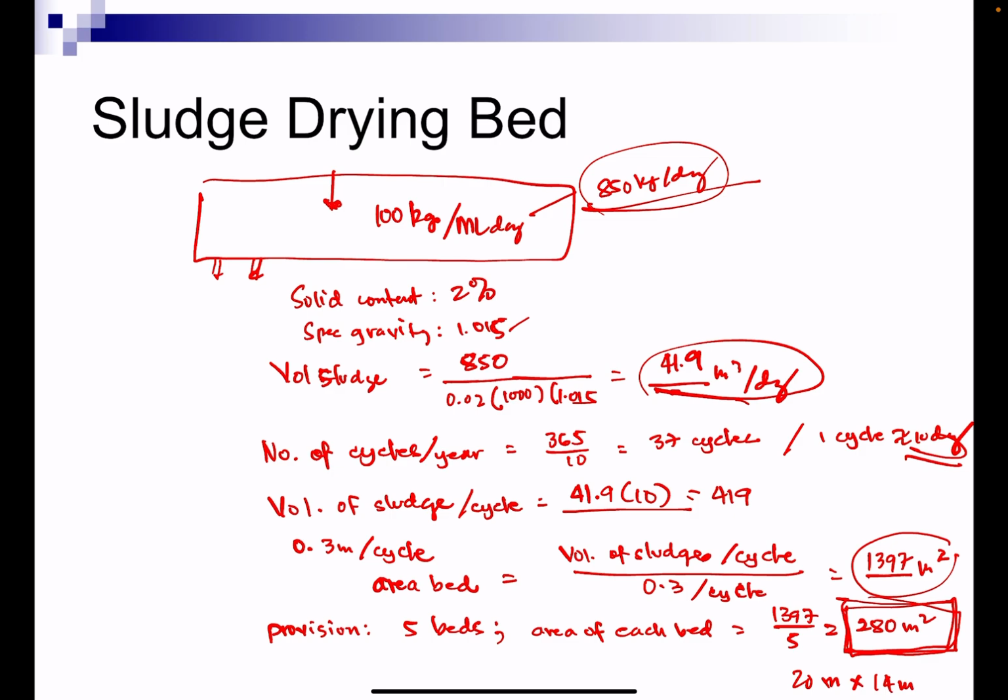Note that all computations will definitely adjust when the actual volume of water supplied is available. For example, if our assumption is on a per capita basis, say 235 liters per capita per day, that is where your computation will start, which is your assumption of the average water supply. And then, assuming the sewage is 85% of that, all computations will roll based on this available water.